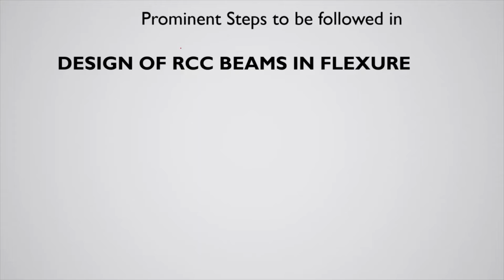And here we will be going to discuss in broad sense that what are the prominent steps which we will be going to follow in case of design of RCC beam in flexure. So very first step will be we have to find out what is the effective span of the beam. So why we have to find the effective span of beam?